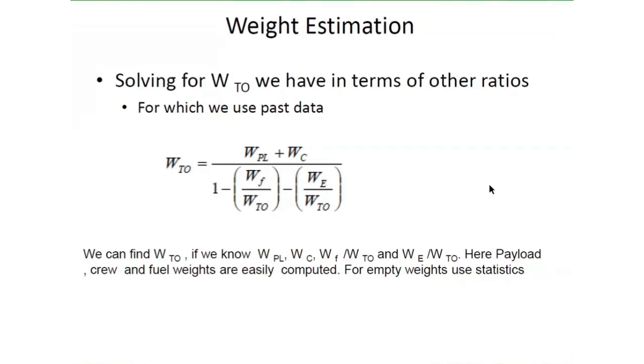So that will give you an estimation of the kind of fuel consumption, SFC, it is likely to have. Now, if the aircraft is going to fly 6,000 kilometers, then obviously it's not going to be a propeller-based aircraft. It's going to be a turbofan-based aircraft. And turbofans come with a certain amount of fuel consumption. Based on that, you can estimate the amount of fuel, the number of gallons of fuel you're likely to use in that flight. So all this can be taken from statistics, and generally statistics is also checked, as well as detailed estimation, for you to arrive at the first approximate estimation of the takeoff weight.